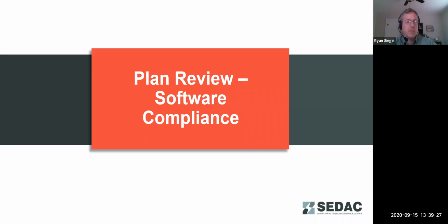We also had another question come in as far as a question on the vapor barrier and where that's located on the interior side of the wall. Vapor barriers are not addressed in the energy code. That is actually addressed in the building code. So the location and permeance of the vapor barrier, you need to reference the building codes to identify where that is. We're just noting that it is good practice to make sure that you identify where your vapor control layers are as part of your design.